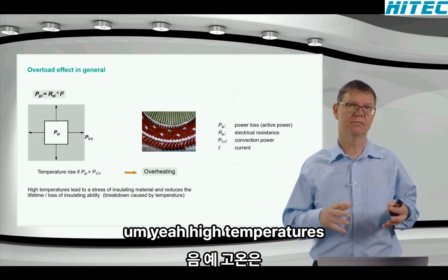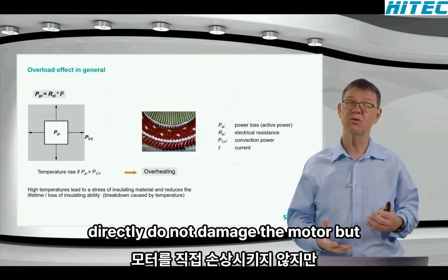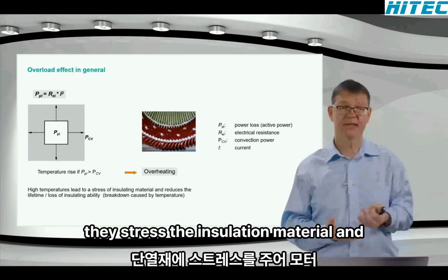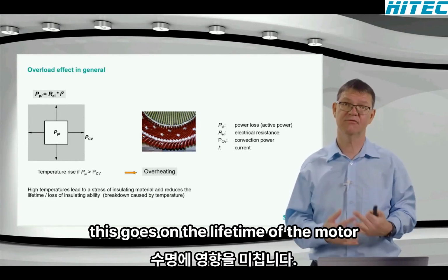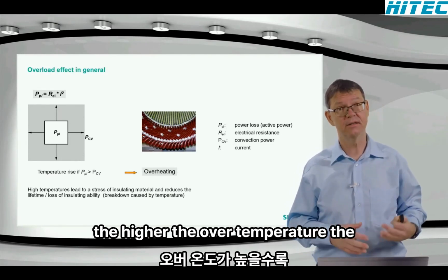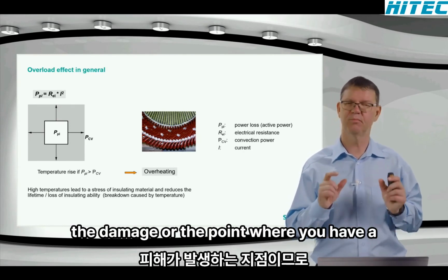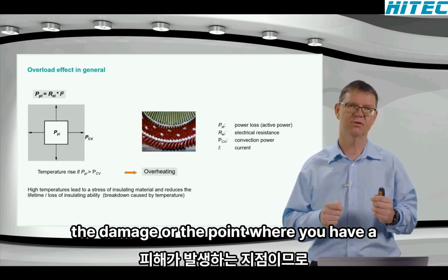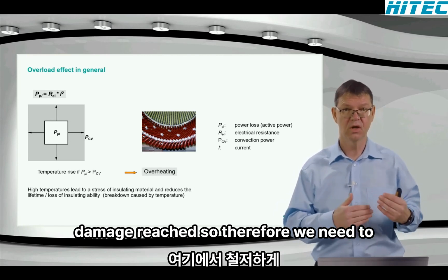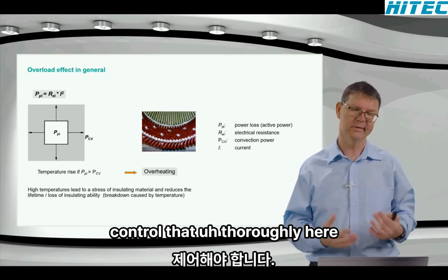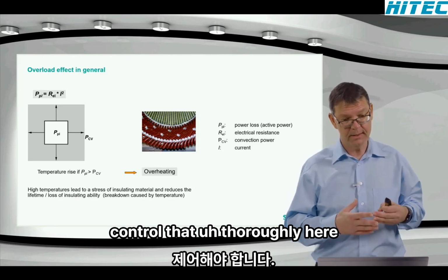High temperatures directly do not damage the motor, but they stress the insulation material, and this goes on the lifetime of the motor. The higher the over temperature, the faster the damage is reached. So therefore, we need to control that thoroughly here.